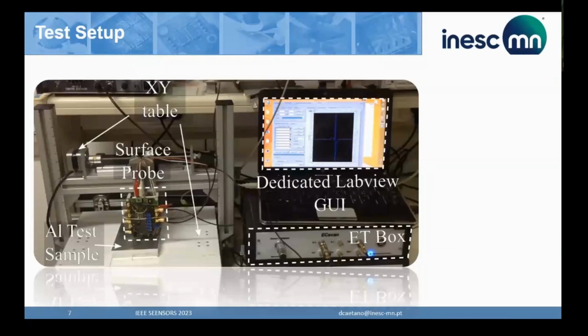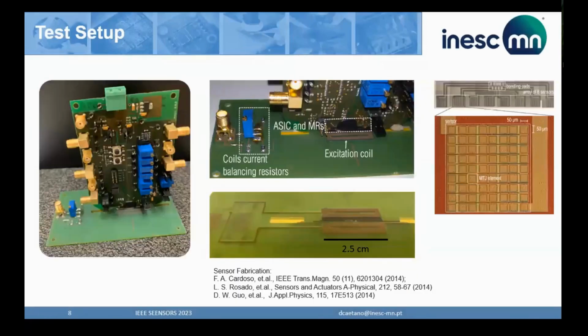So this was done by several people. The probe actually looks like this without its casing. So this is just the open version with the PCB for interfacing electronics, but the sensors and the coils here. You can see the excitation coil is a little larger than the sensor, which in this case is just this area. And the sensor in this case was a series of 72 magnetoresistors, with around 20 kilo ohms of resistance. Magnetoresistive sensors basically have a lower limit of resistance and a higher limit of resistance, and then a linear curve that depends on magnetic field.